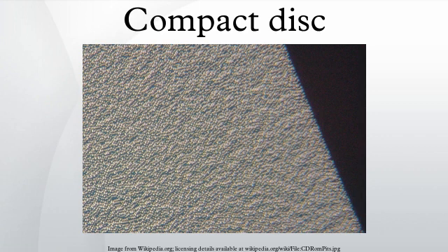This in turn is decoded by reversing the eight-to-fourteen modulation used in mastering the disc, and then reversing the cross-interleaved Reed-Solomon coding, finally revealing the raw data stored on the disc. These encoding techniques were originally designed for CD digital audio, but they later became a standard for almost all CD formats.